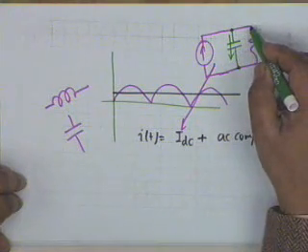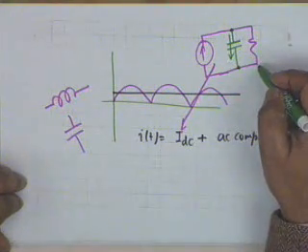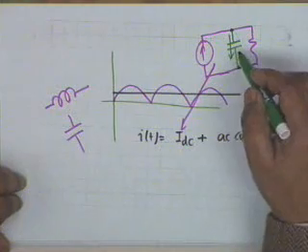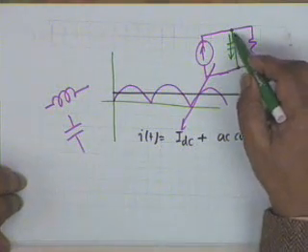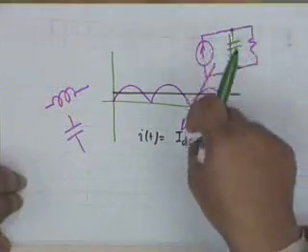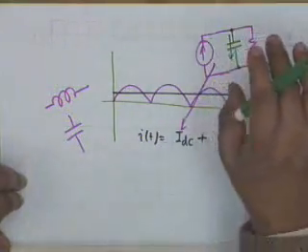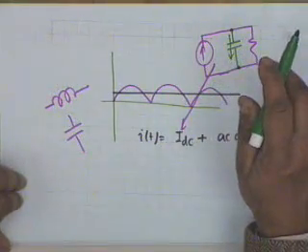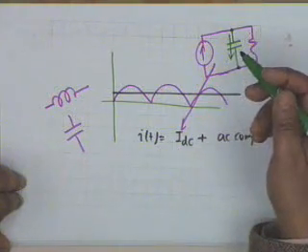It is the DC which passes through the resistor, and therefore as far as AC is concerned, the capacitor provides an easy path, so most of the AC flows through the capacitor, nothing goes to the DC, to the load. All right. This is what basically filtering is.